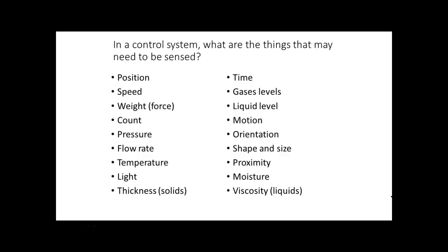And of course, this sensor right here senses temperature. This gives us the ability, and we'll talk about it later on, to set what we call the span. Notice it's got two bands on it. Y'all know what that probably means? The range of what's true and what's false. Some sensors will switch at the same level. This sensor right here, we can make it give us one indication when it gets above a certain temperature, and another indication when it gets a lot lower. And y'all be making runs down to the cafeteria to get ice for that.